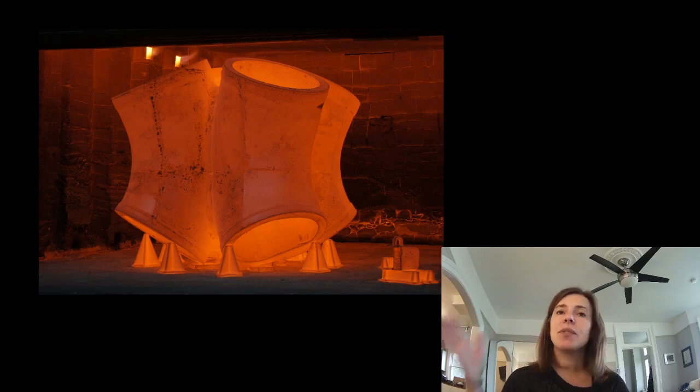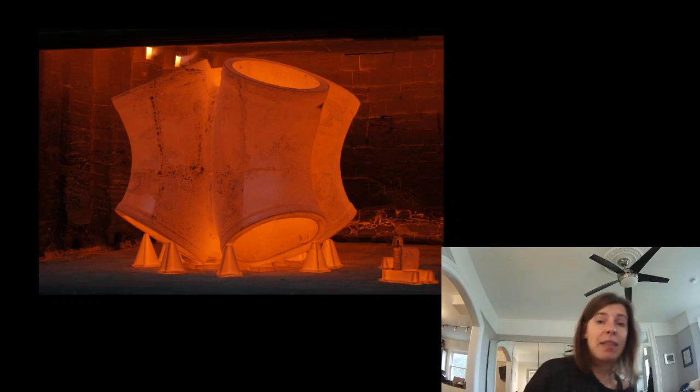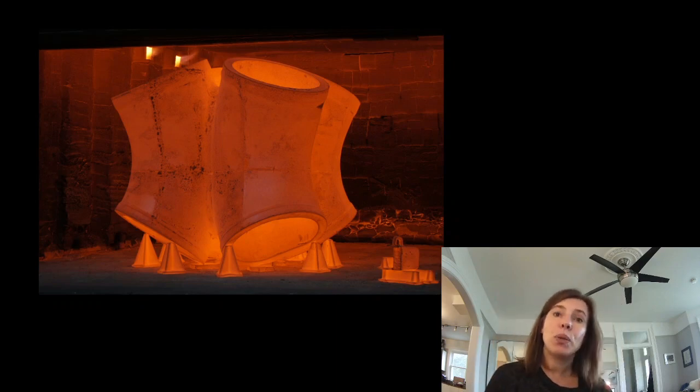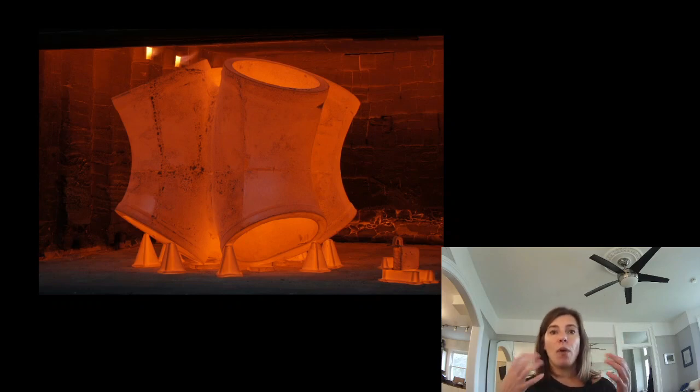After they cast it using the same method, the sand cast method that I showed you with the Pompidou Gerberettes, where they would create a foam or wood positive, and then a negative with sand, and then they fill it with molten steel. After they do that and they knock off all the bits, just to help ensure that the stresses are equalized, they'll reheat it and control the cooling process.